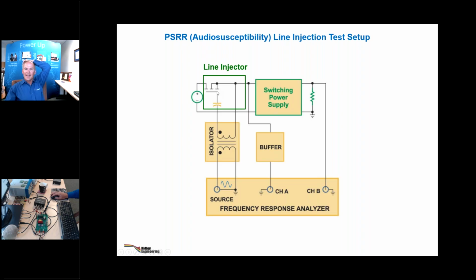You have to heat sink the FET because it's going to take the full input current across it, and it's going to have a drop across it. Depending on how well you set this up, that could be a significant amount of power that you need to heat sink. So loop is invasive. Output impedance is less so. This is very invasive into your power converter system. If it's a 400 volt input, you really don't feel like doing this, because this is hard, and it can be dangerous if you're breaking that high voltage bus.